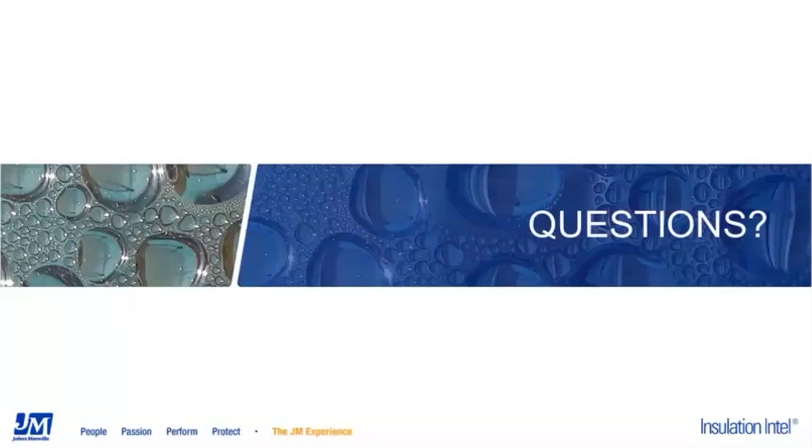So you have to start thinking about heat tracing the pipe. You have to put heat tracing on there. That's something that JM can help with a little bit. We aren't heat tracing experts, but if someone tells us the amount of heat that is coming from the heat tracing, we can balance that against the heat loss through the insulation system and tell them an insulation thickness necessary to get that balance and hopefully then achieve the freeze protection.